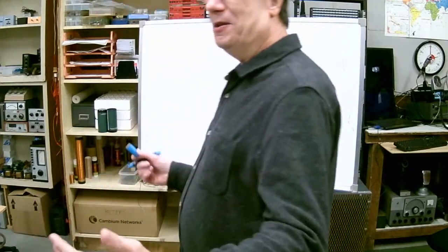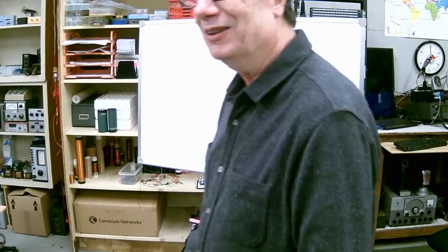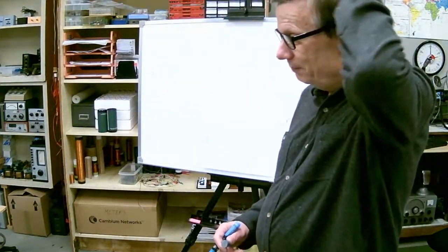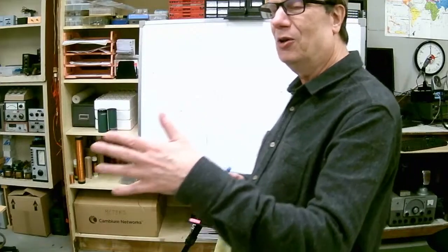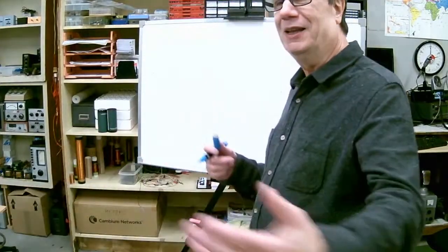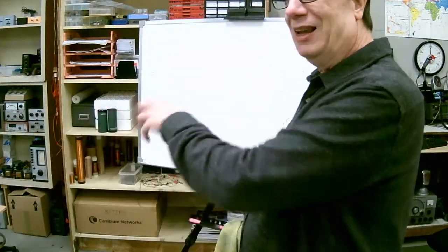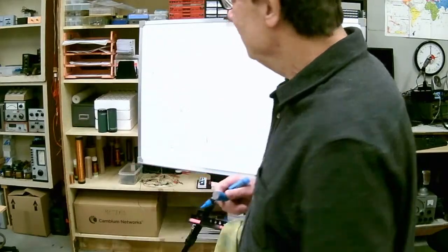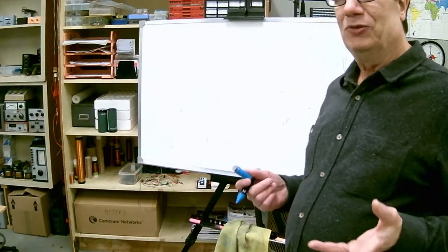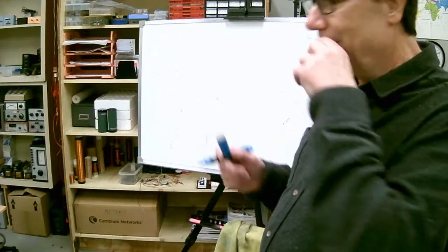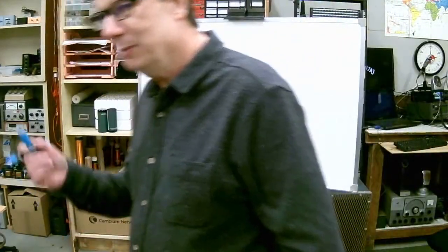Everybody gathered around and watched the radio, because that was a little bit of entertainment. They had 3 tuned stages, so rather than doing it all in one stage, you distributed the gain over multiple stages. So you had 3 tuning dials, and they're all tuned radio frequency amplifiers, tuned at the incoming frequency.